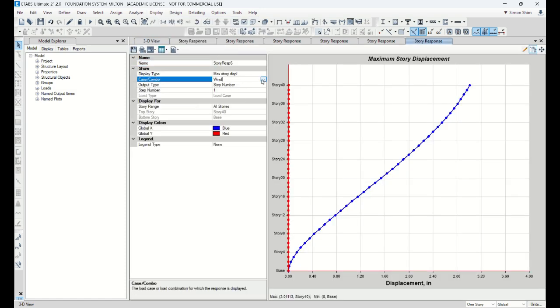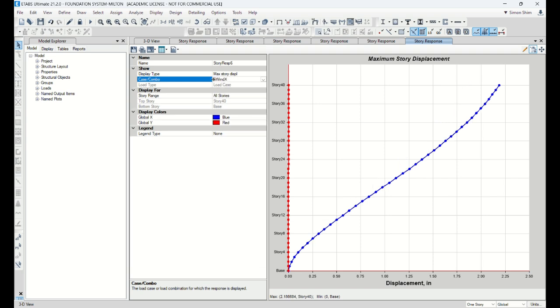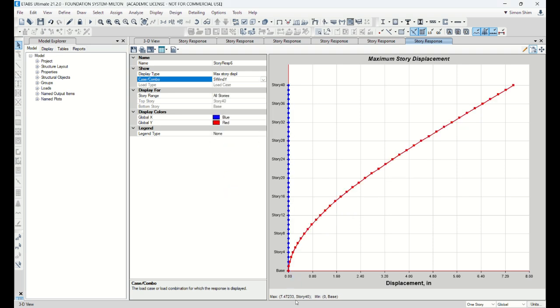The deflection due to the wind, let's say X. The maximum story displacement in X direction, you have a 2.18, which is actually reduced a little bit. Y direction used to be 14 inches, now 7.4. So basically, your building has a very deep, 50 feet long wall, and also in X direction it is much longer. So you have a tremendous amount of stiffness, so you don't have any issue.